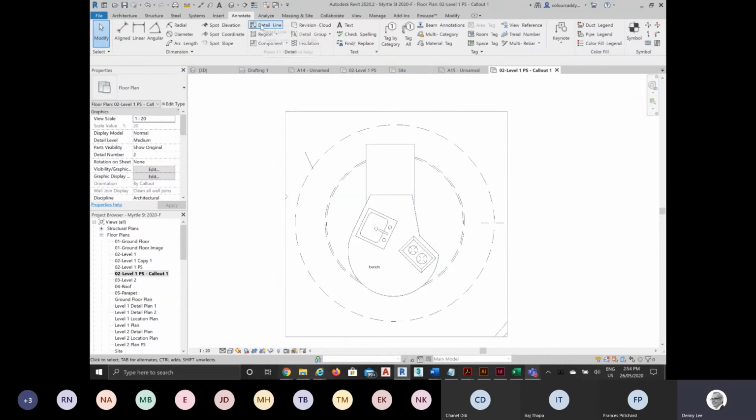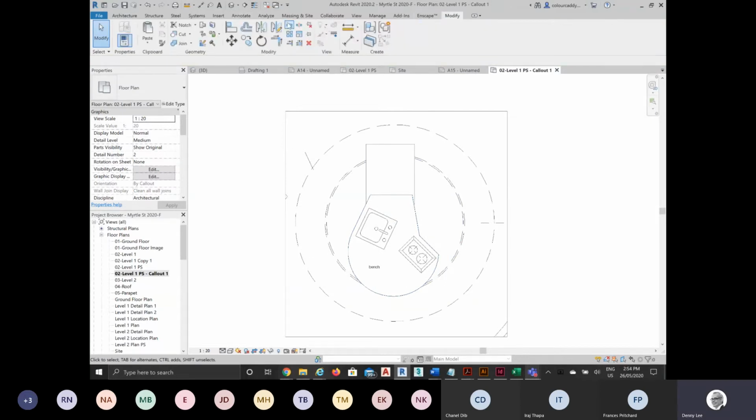Okay, so again, with the split element tool now, I just need to choose it at one point. And we're all good. Then again, with trim to corner, I can choose the circle and then the line, and notice how it's broken it, or taken it back to this point here, where I split it. So now I can do the other side, and it's much clearer then how it's working. Okay, so it's just that split element tool.